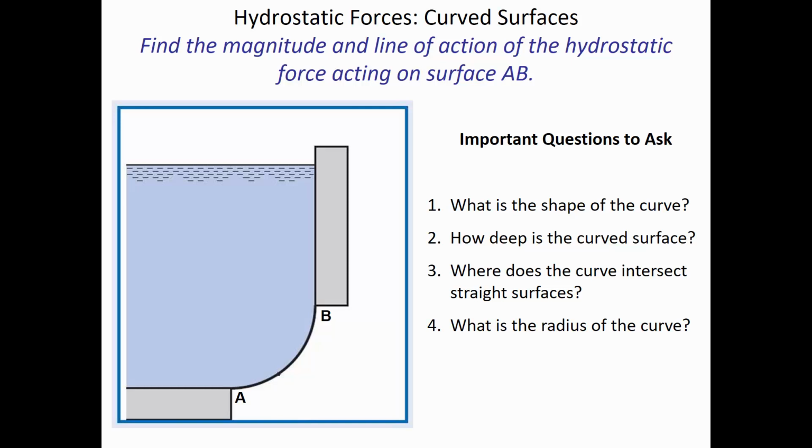And so what we're trying to find out is what's the equivalent hydrostatic force and where is it? If we were going to say force is pressure times area, we've got a bunch of little pressures, and we could divide that curved gate, if we were looking at it from the front, it would look like this. We could divide it up into little elements, these tiny little segments, and say, what's the pressure acting over that element? Pressure times area.